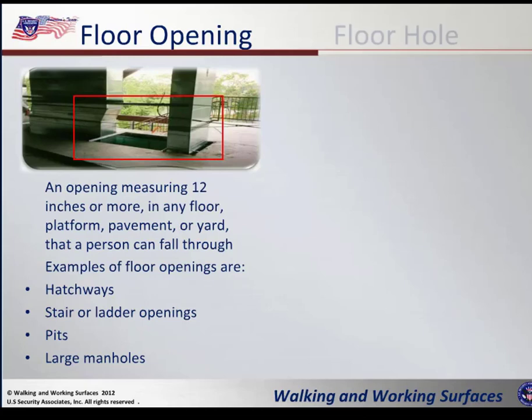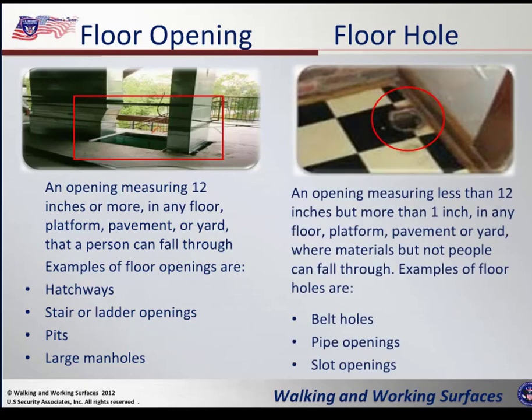Now, a floor hole. What's the difference between a floor opening and a floor hole? A floor hole is an opening measuring less than 12 inches, but more than an inch, in any floor, platform, pavement, or yard where materials can fall through, but not people. Examples of floor holes are belt holes, pipe openings, slot openings.